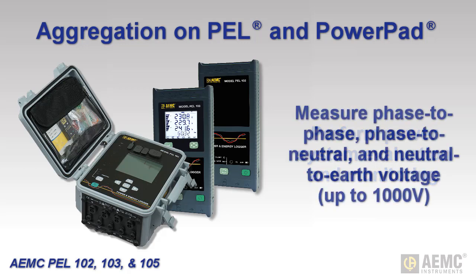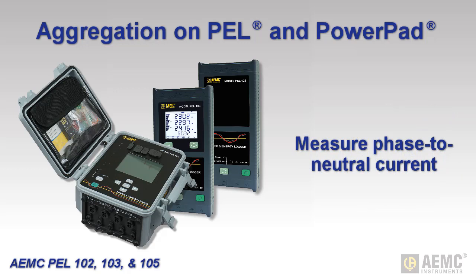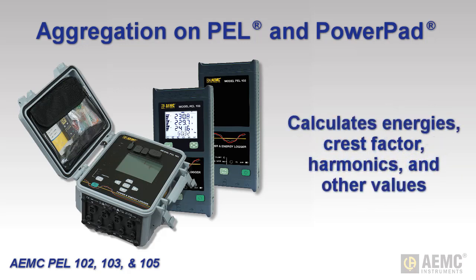These instruments measure phase-to-phase, phase-to-neutral, and neutral-to-earth voltage, measuring up to 1,000 volts. They also measure phase and neutral current, using a variety of external current sensors. Measurement data is then used to calculate numerous values, including active, reactive, and apparent power and energy, crest factor, harmonics, and total harmonic distortion, and others.